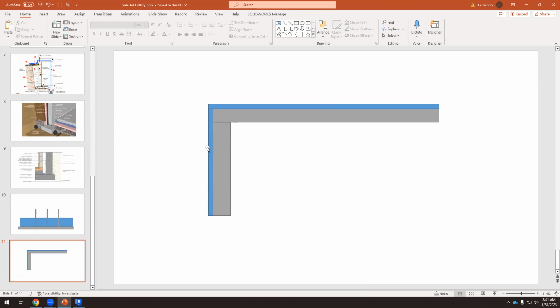So usually it's centered because it's easier. But if we can't do that because we can invade our neighbor's site, or imagine that we're building something within two different buildings, so we can't dig in that building because we will affect their own foundations. So sometimes we have a footing that is not centered.